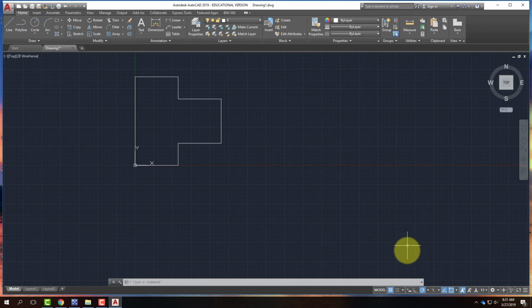At this point, I'm going to go ahead and turn back on dynamic input. So remember, it was that button down here at the bottom that had a plus sign and then a filled in little rectangle. I'll turn that back on. Most of the time, this will be on by default in AutoCAD. And what this allows me to do is, as I start drawing, you notice that instead of just having a cursor, there it is with it off, when dynamic input is turned on, next to my cursor, I have the ability to specify a start point, and it's giving me information right there.